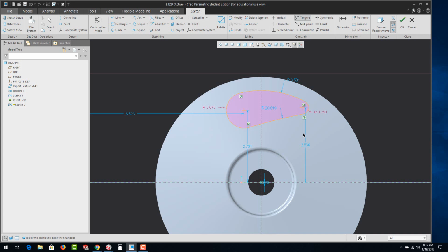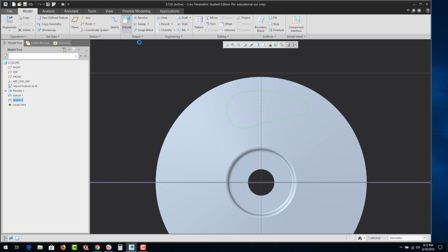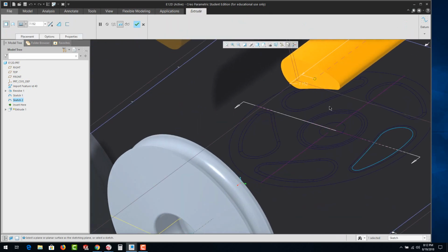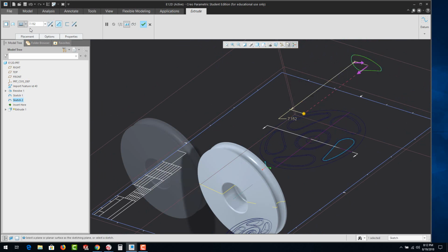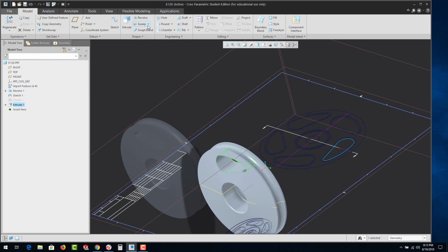And so now we've tried to preserve the geometry as best as we could and repair it at the same time, because when it had those red dots, we'd have some issues trying to extrude those. Like I said, that's an indicator of a sloppy sketch. Okay, so now we could hit OK, and we could go to extrude. And let's rotate. We can see the extrusion right here taking place. We actually want to remove material, so make sure you select that. And then over here, select that you want to go through all. Hit the green check.